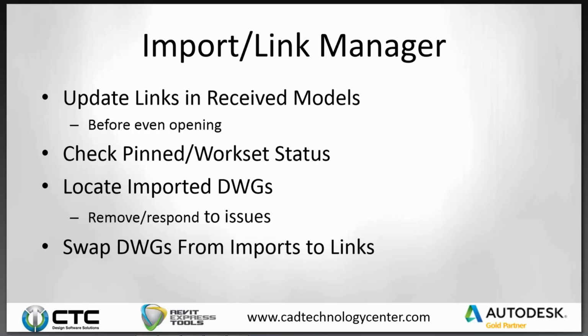And the Import Link Manager can actually help you find imported DWGs, find the views that they're in, and in most cases, swap those DWGs from imports and turn them into links. So you can actually fix the problem that might have been generated there. So those are four major features that Import Link Manager can help you out with in the cleaning and maintenance of your projects. So with that, what I want to do is jump into Revit, and we're going to take a look at how this can work.